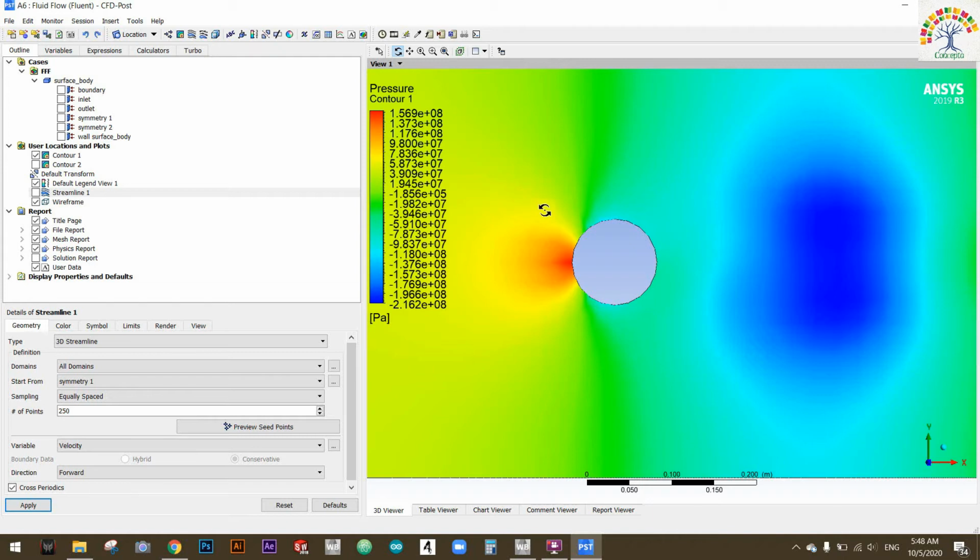What does it state? That the sum of static pressure, the dynamic pressure, and the head is a constant. In this case, there is no head, there is no height or rho gh. We're working with air, so the rho, the density, is really small. Any height does not matter. So there's only static pressure and the dynamic pressure. Notice that static pressure is simply pressure and dynamic pressure is caused by velocity.